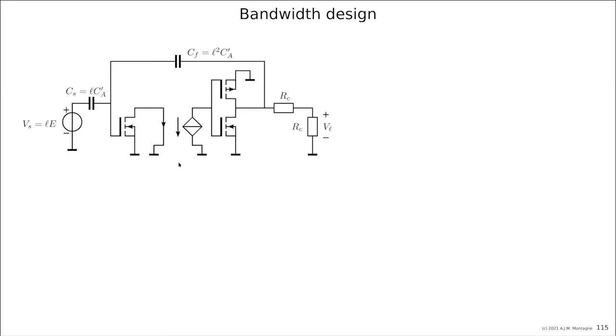Here was the idea. I said before, if we have two non-inverting stages, then we can use a differential pair, for example, as input stage here, to take the other output terminal and have an inverting loop transfer instead of non-inverting. That is probably the best solution, and we left it up to you. So you have the honor to do the best solution. Let us work with some inferior one, just for the demonstration of the process.